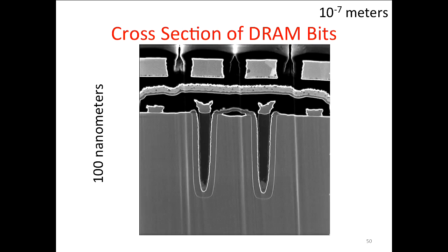How often does DRAM refresh itself? The question was how often does DRAM refresh itself these days. It doesn't refresh itself usually. Usually the controller tells it to refresh, but you usually have to hit every bit every 64 milliseconds, which is the industry standard. So every tenth of a second, or a bit more frequently than that, you have to go back and refresh every bit.